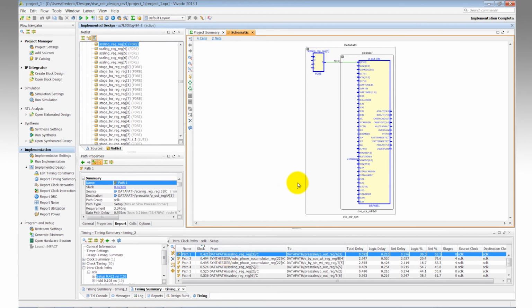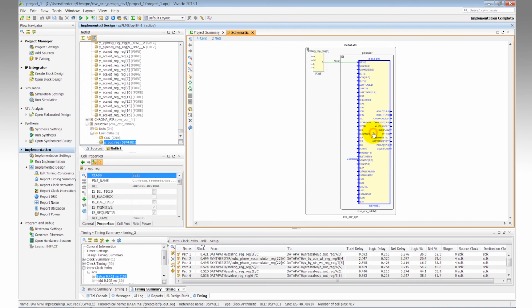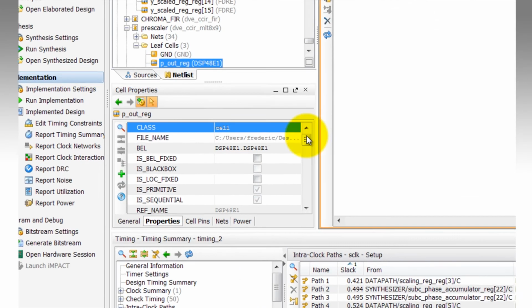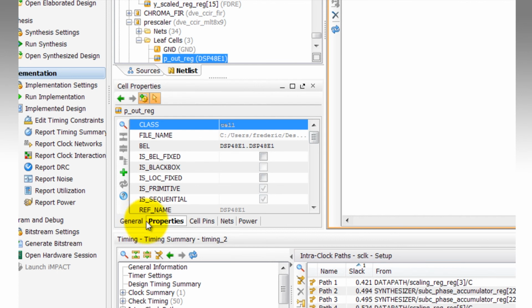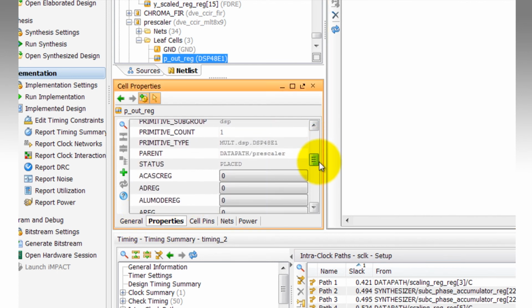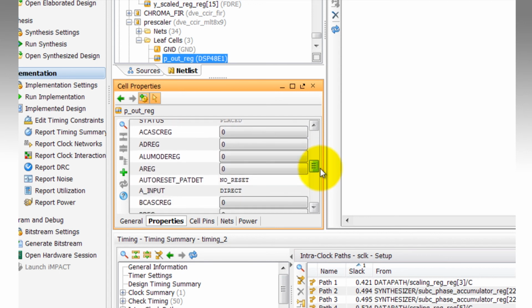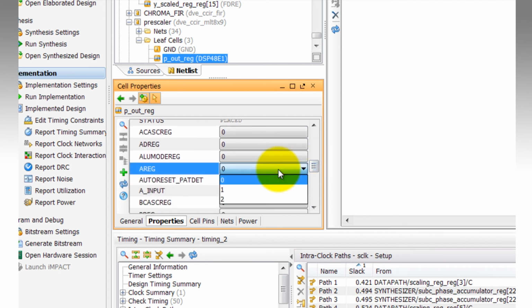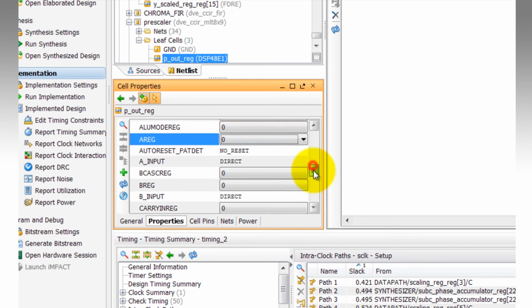We see that it involves a multiplier, which is not a surprise since we knew from synthesis that they were timing critical in this design. To better understand multiplier performance, it is useful to check how pipelined they are, and this information is visible in the Properties window once the object is selected.